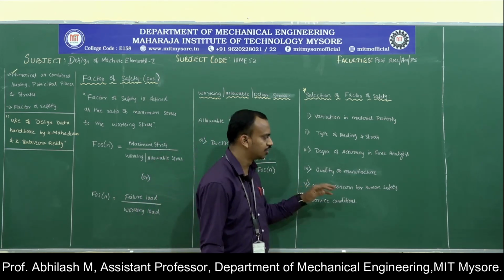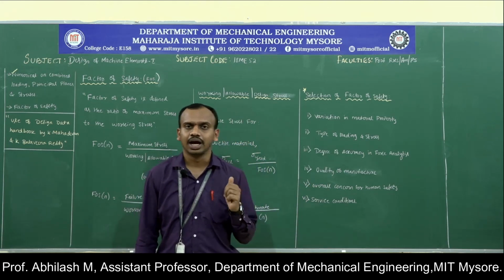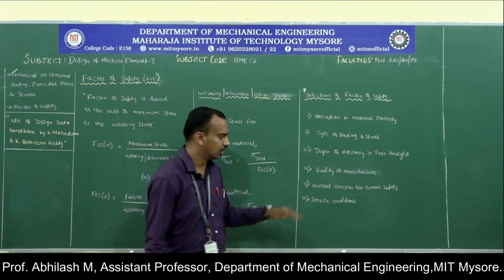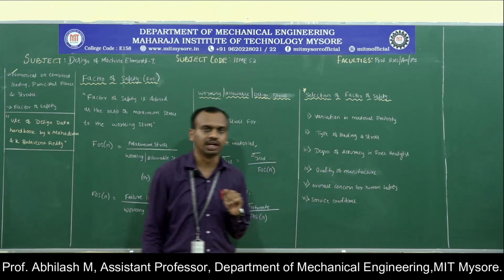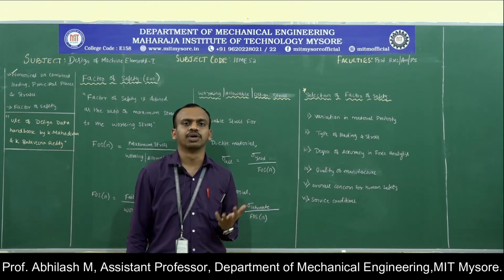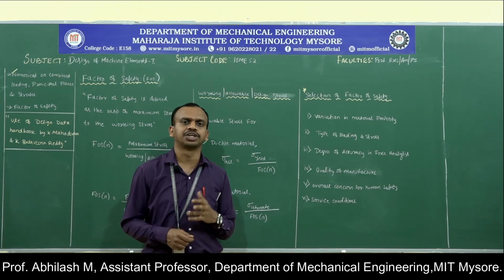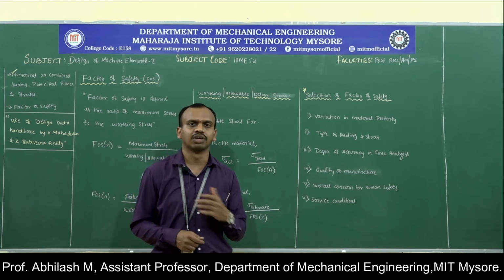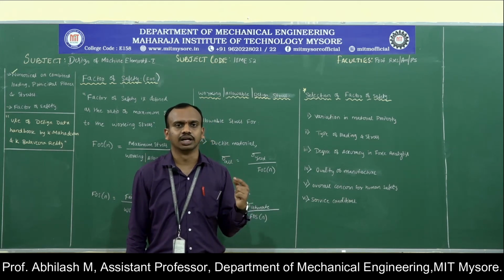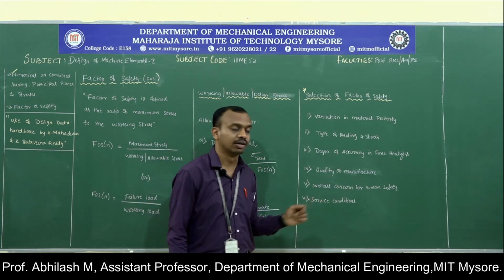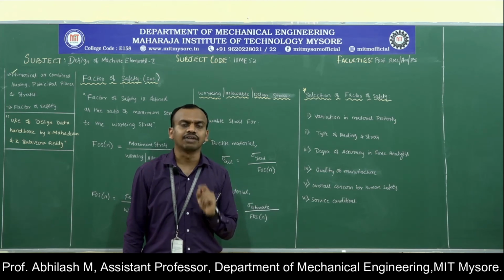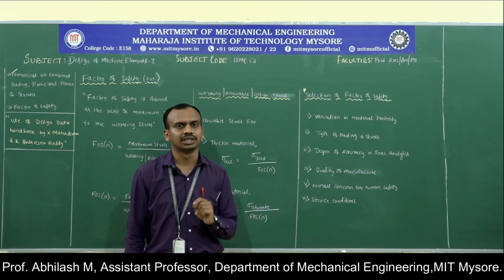The overall concern for human safety plays an exceptional role while selecting a factor of safety. In other words, it depends on what conditions the machine components are operating in. If it is pressure boilers or pressure vessels, the factor of safety value should be higher in nature, because the workers will be working in that particular environment for a longer period, and if a failure happens, the result is havoc.